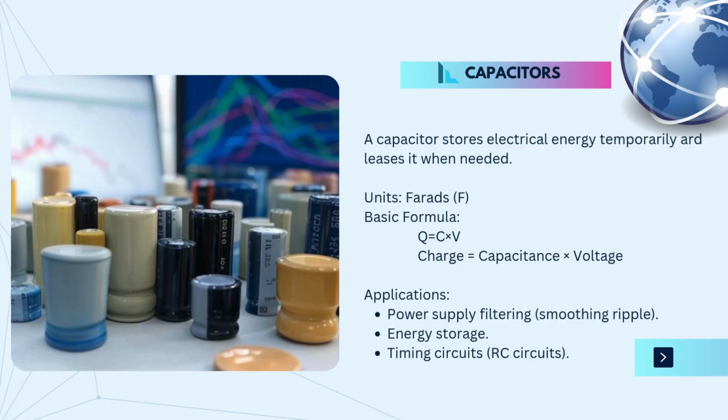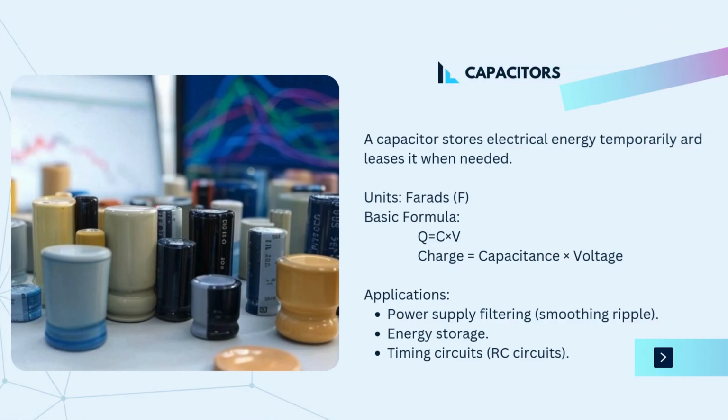Behavior. Charges up when connected to voltage. Discharges when disconnected. Applications. Power supply filtering, smoothing ripple. Energy storage. Timing circuits, RC circuits. You'll often find capacitors next to microcontrollers on PCBs, filtering noise and providing stable voltage.